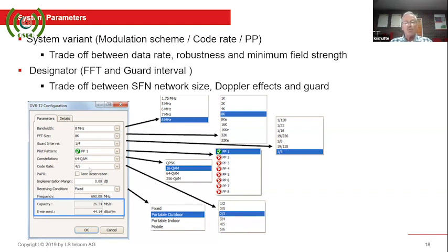The code rate or forward error correction, that's also important, and one needs to go for a typical code rate. And you can also look at the standard configurations, which are recommended by ITU, for a combination of transmit parameters, which have been tested worldwide. So one can use the guidelines from the ITU in that.